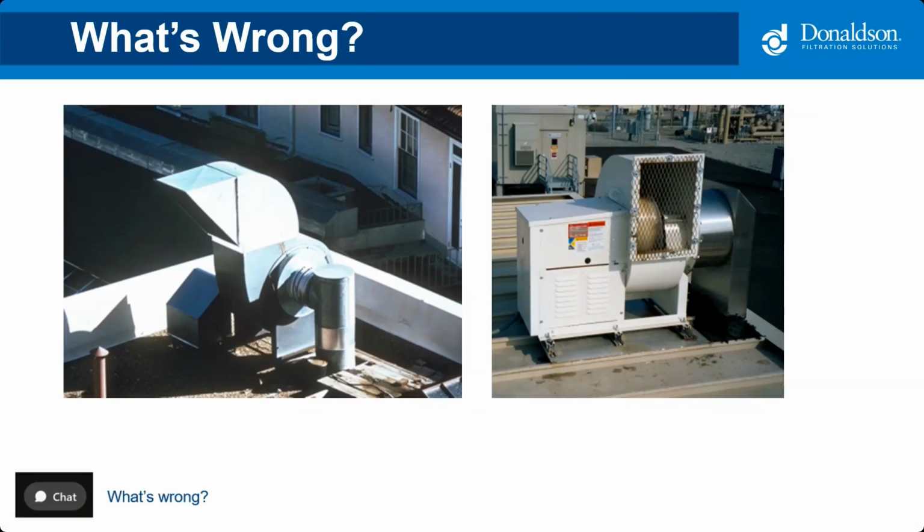Yeah, I think you're nailing it. That's exactly what's going on. That one on the left, like we mentioned, we want a nice linear full flow inlet to the fan. And this is so compromised. I'm surprised the fan might do 10% of its capacity. The flow is just so restricted with that small inlet and the 90-degree fitting right in front of it. It's just not going to work well.